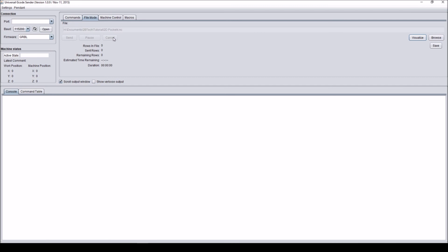This concludes this tutorial on walking through step by step how to take a Solidworks file to G-code and then send that G-code to a CNC mill, most likely a Shapeoko for these circumstances. It should be stated that additional tweaks to feeds and speeds will most likely be necessary after your initial cut to ensure that your cutting tool is cutting properly at a safe depth, as well as cutting quickly enough to ensure you do not overheat the bit or the part.